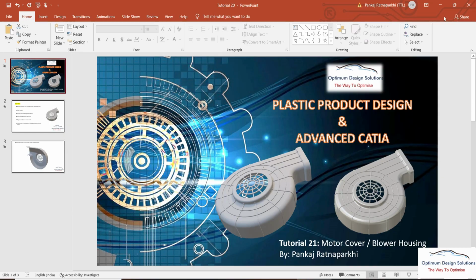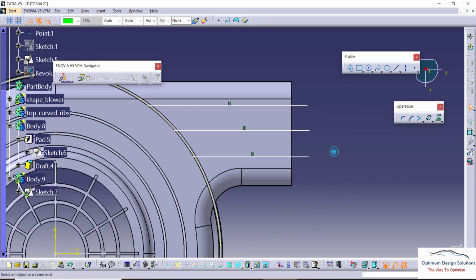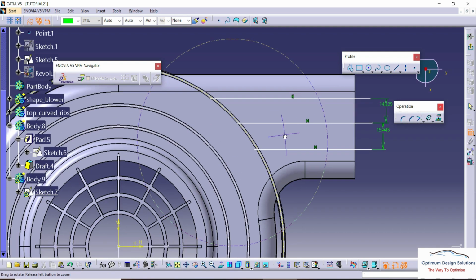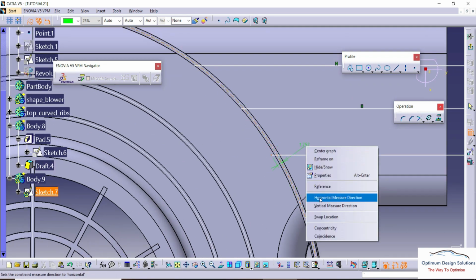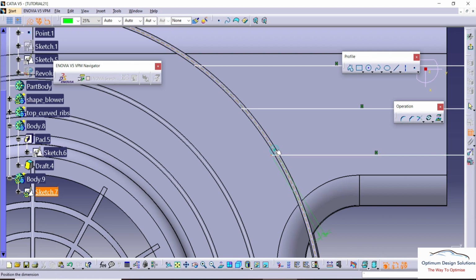So here the three ribs are added at that area, so it totally depends upon the area of that particular duct or outlet area. Here we used almost 70 mm, so 2 or 3 ribs are sufficient for providing that support for the material.